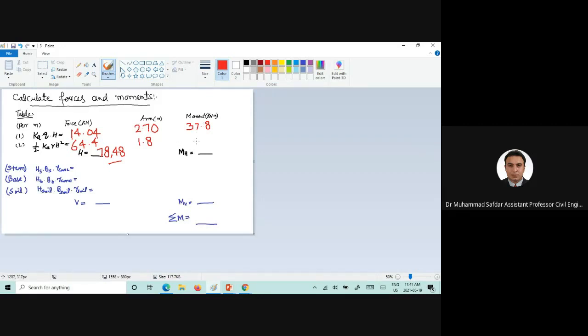Due to the backfill material, so that was due to the surcharge, 115.9. And please kindly add these two moments as well. 153.7 would be the moments which are occurring due to the horizontal force. Okay, so please kindly note down these two values because we are going to use them for finding the overturning, sliding resistance, stabilities, and limit states.